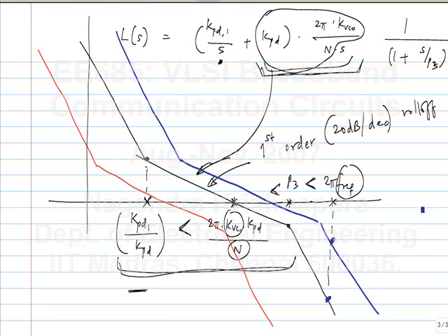One of the other issues, this is just the plot of the loop gain, okay? And from this you can get the closed loop gain and other transfer functions. Now every component in the phase locked loop is non-ideal. It will inject some kind of non-ideality at the output in addition to its ideal output. So what you have to evaluate is the transfer function from every one of those non-idealities to the output and see how they are affected, okay? Now all of these transfer functions from anywhere to the output will have the same poles, but they will have different zeros, okay? So we have to evaluate those things also before we see whether to make, for instance, this particular value small or large, how large we can make it and so on, okay?